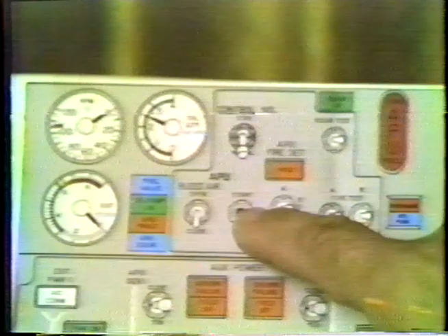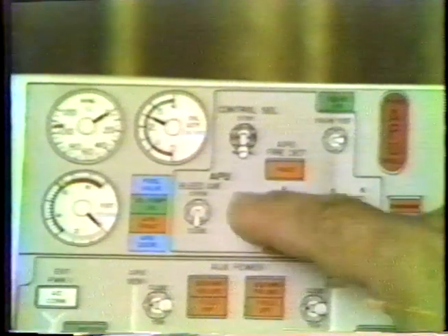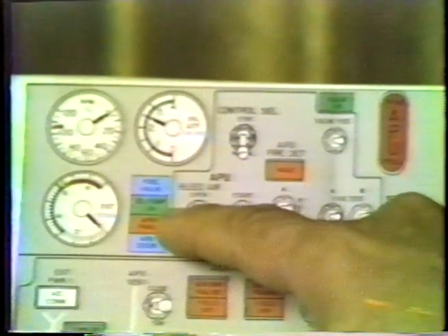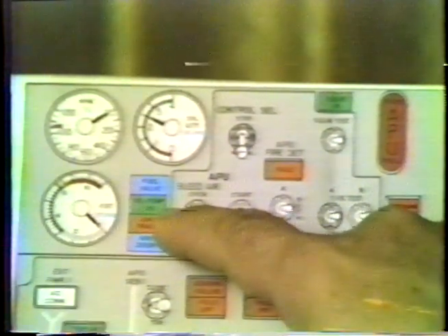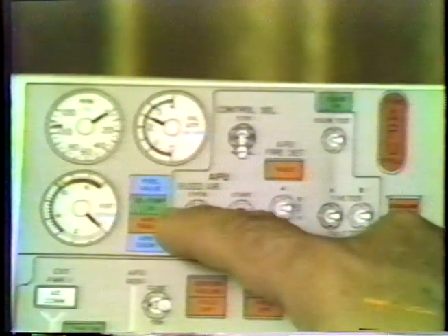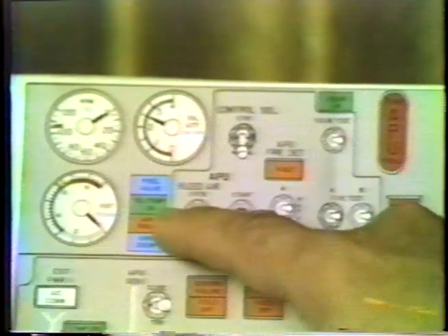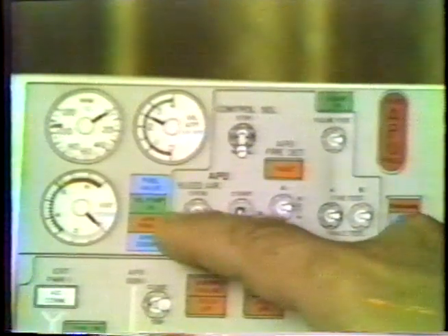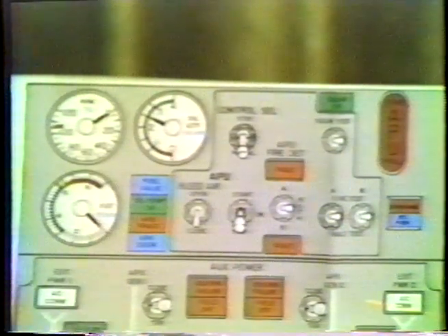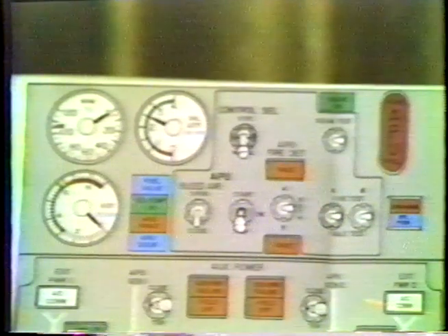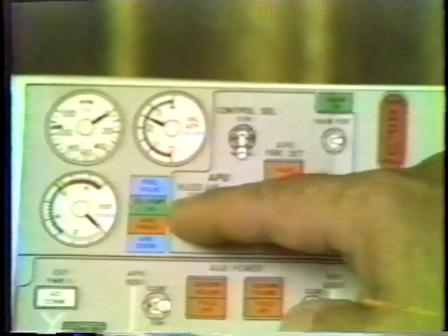On moving the switch to on, if no power is available on the aircraft other than the aircraft battery, you will see a DC pump on light illuminate to supply fuel from the number 2 tank to operate the APU. If aircraft power or ground power is available, the DC pump on light will not illuminate, and the fuel will come from the number 2 main tank with the number 2 aft boost pump pressure light going out. If the pressure light does not go out, then the green light will come on to supply the fuel pressure.